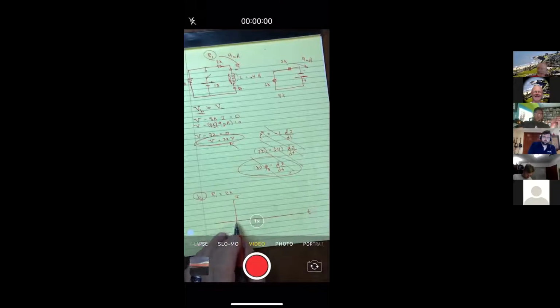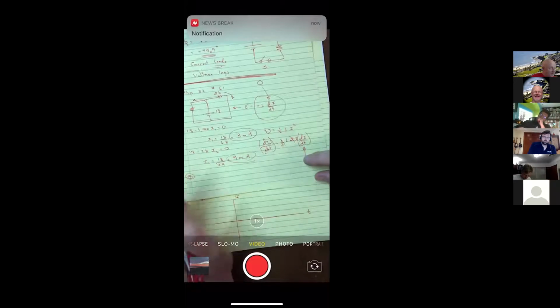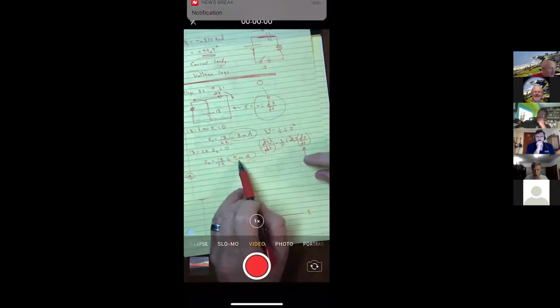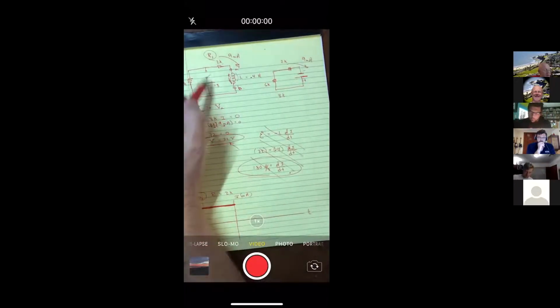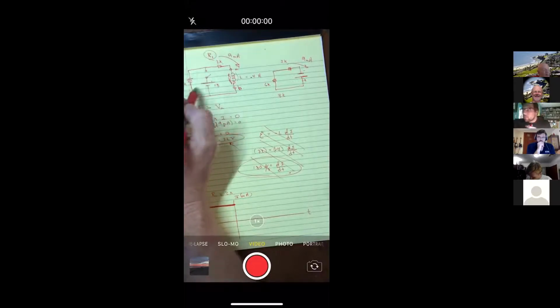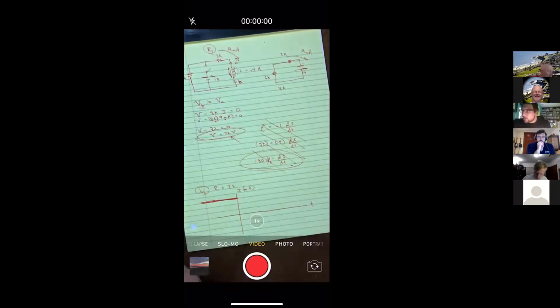All right. So as we said earlier in the problem, before the switch is open, we reached a steady state for number 2 at 9 milliamps. So if in my graph I use each line as 3, this would be 3, 6, 9 in units of milliamps. And so for time less than 0, I would have 9 milliamps. Of course, somewhere over here we had to turn on the switch, but I won't graph that. So I'll just say, okay. So for all times less than 0, the switch was closed and we had 9 milliamps going around the right loop and 3 milliamps going around the left loop. But I'll worry about that one. And they said in the direction of steady state, so I made it a positive 9.